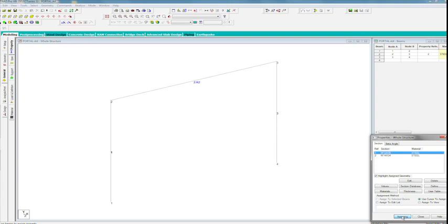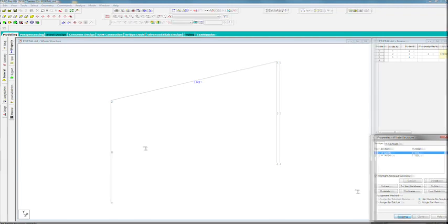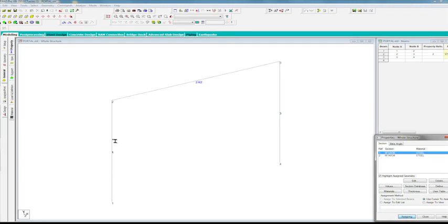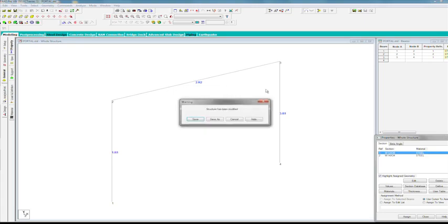We're still on Cursor to Assign, and click Assign again. Go to the 2 columns and assign the 12 by 35 to that. And then we can turn off assigning, and we've completed that. Once again, we don't want to lose anything, so we'll come up and save our work.